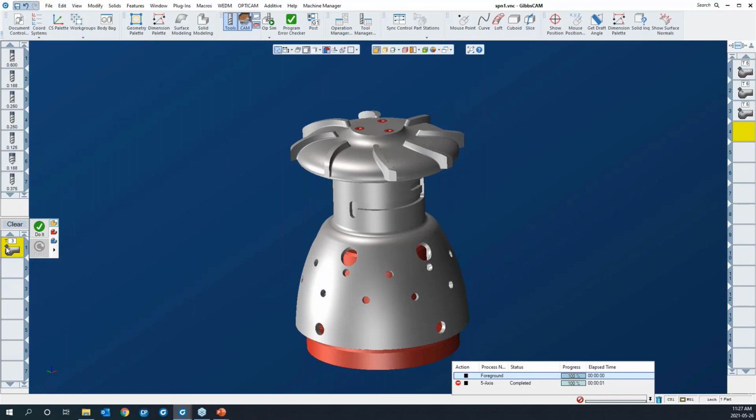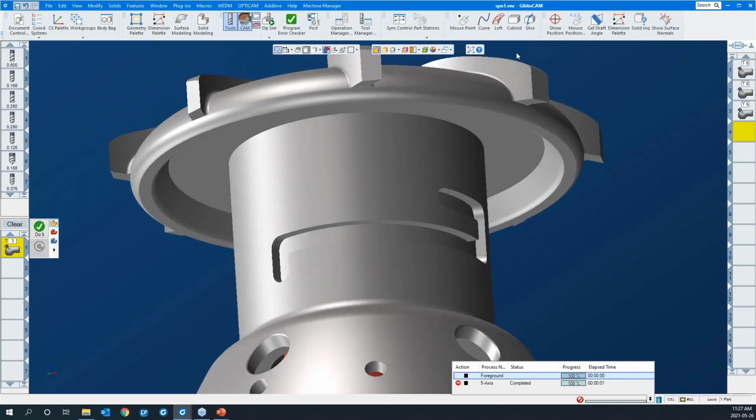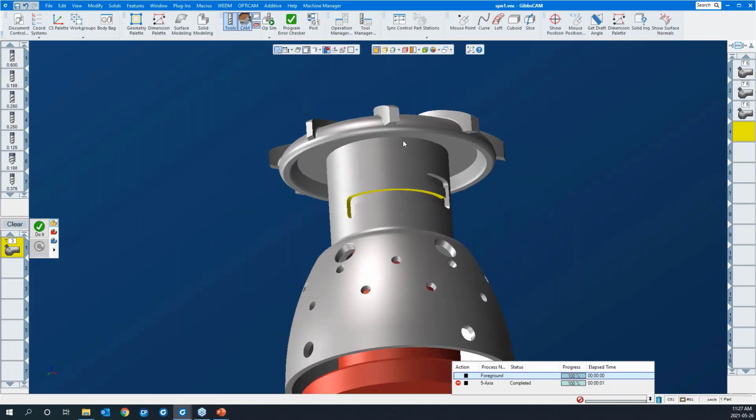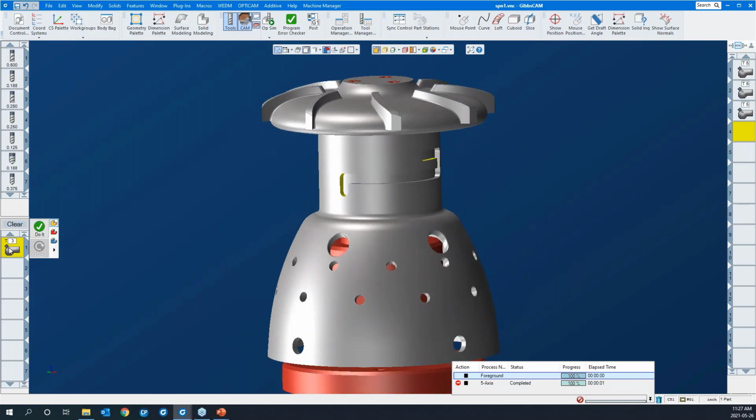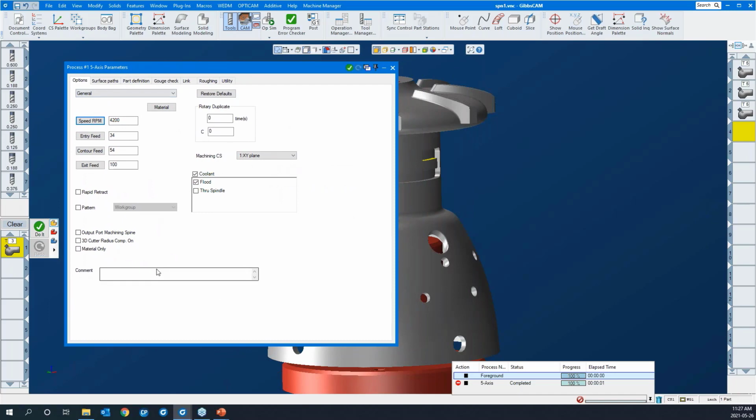We'll let it load up. It's using T3, tool 3, which is a 1/4-inch end mill to cut this feature. We can measure the width of this slot rather quickly. I'll just measure across the width of the slot, and the slot's 3/8. So our 1/4-inch tool should fit the bill for a very quick and effective roughing strategy here for some of our 4-axis work.